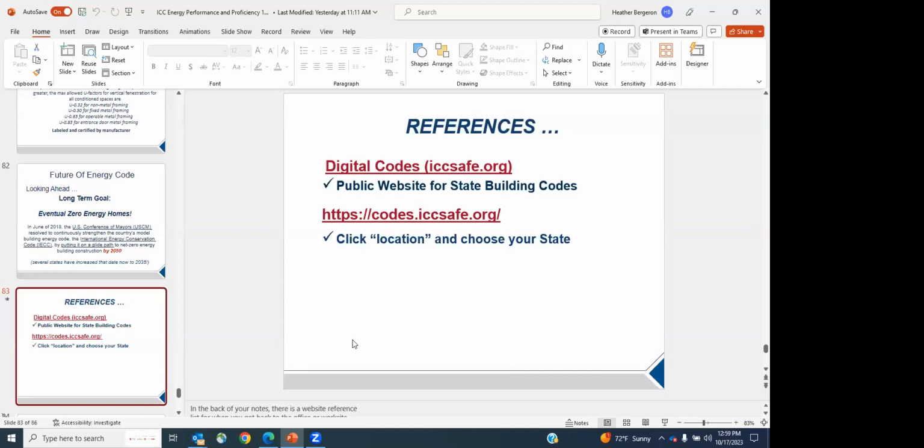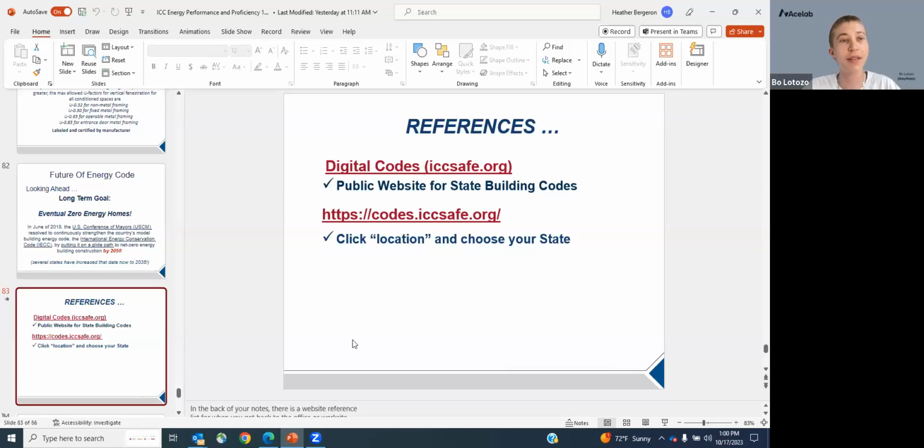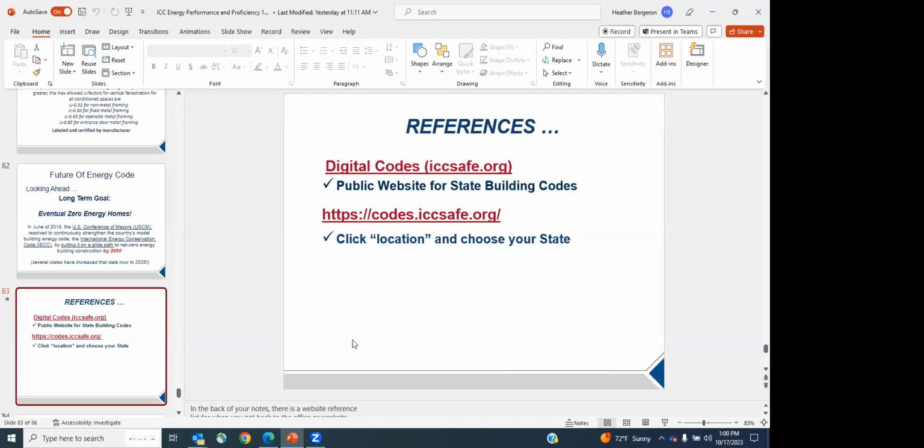If it's up north, then they'll put it on surface number 3 because it will help more with the U factor. Whereas on surface number 2, down south, it works better for the solar heat gain, and we want to prevent that heat from coming through the glass. You don't have to specify as an architect where to put it. You just have to provide the manufacturer with the energy numbers that you want, and they'll determine where it belongs.